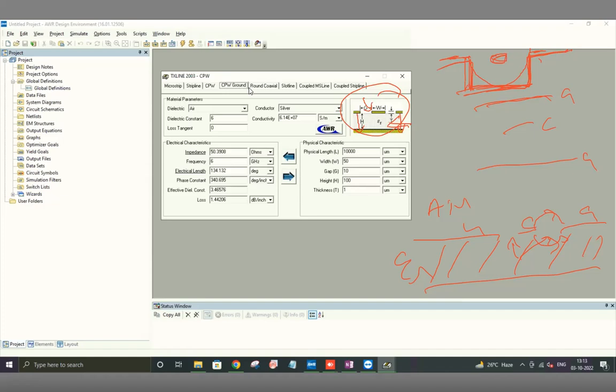In case of coax, it's quite a round shape. Oh, you mean because it's round? Yeah. With round we don't have a problem, but when you restrict things. For example, one can make a coax which is sort of rectangular in shape. I can make the outer body like this and the center pin like this, and there's no problem. This also will support a TEM mode. So sharp edges can have other types of effects which are not directly related to the transmission line properties,